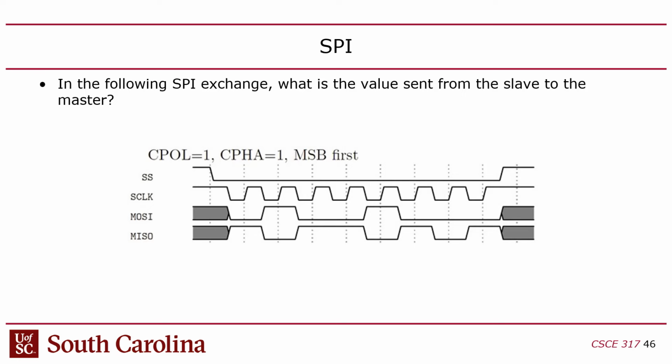It's kind of ambiguous which state the line is on. Yeah, exactly. When it reads, the data is also changing on that same edge, right? So ideally, you want to read the data on the opposite edge from the one on which the data is changing, right? So that way, when you read the data, and Angela mentioned this, but she didn't emphasize it. She said the data is stable. What that means is that the data had been set up a half clock cycle earlier and is not going to change until a half clock cycle later.